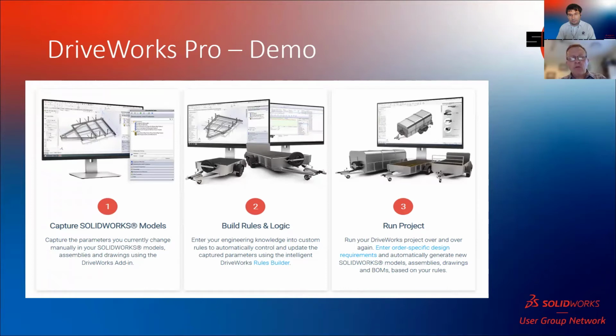You then build some rules and logic in DriveWorks modules themselves that link back to the information that you've captured inside SolidWorks. And then you run the project. By running a project, I mean you see the forms you've created and you enter the data you want, and that data is then fed back into SolidWorks, and SolidWorks generates the new models for you.